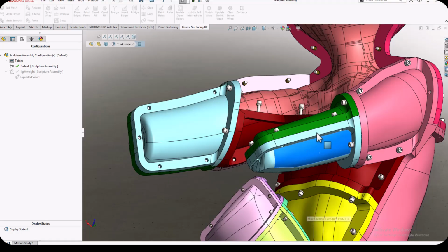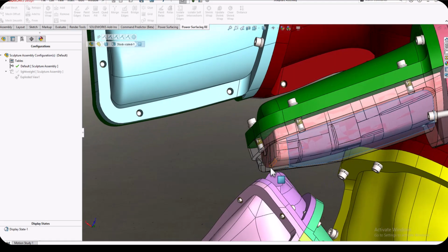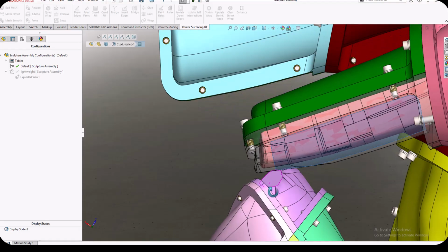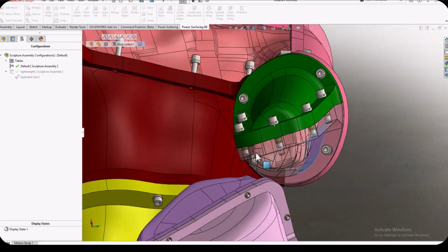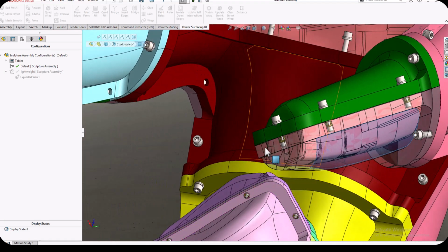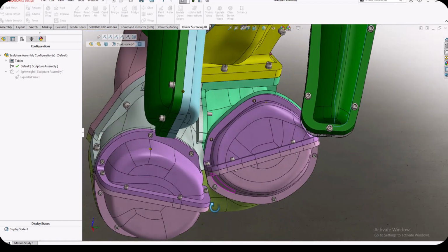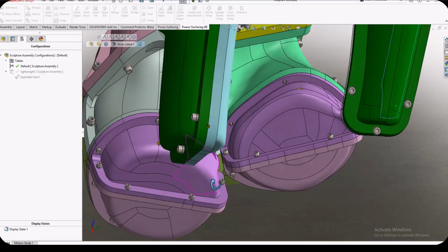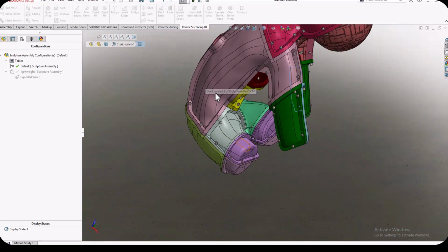For example, imagine trying to remove this section. As you pull it downward, the sculpture's arm could interfere with the movement and cause the mold to catch. Because TPU behaves more like rubber, you can gently flex the mold while slightly rotating or tilting it, making removal much easier without damaging either the mold or the sculpture. These small design decisions can make a significant difference in the success of the final mold.